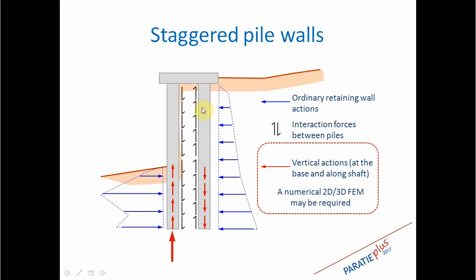that can be provided either by the soil in between piles or by the grouting that interferes from each pile to the other piles. And if the distance between the two rows of piles is big, there is also a resistance due to each pile also acting as a vertical loaded pile, and we may have a base resistance if the pile is in compression, and also a shaft resistance.